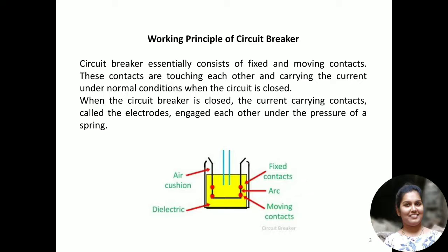All the circuit breakers have operating coils. Whenever these coils are energized by a switching pulse, the plunger inside them is displaced. This operating plunger is typically attached to the operating mechanism of the circuit breaker. As a result, the mechanically stored potential energy in the breaker mechanism is released in the form of kinetic energy, which makes the moving contact move, as the moving contact is mechanically attached through a gear lever arrangement with the operating mechanism.